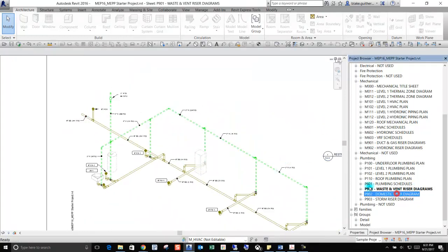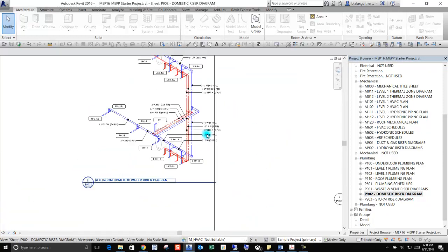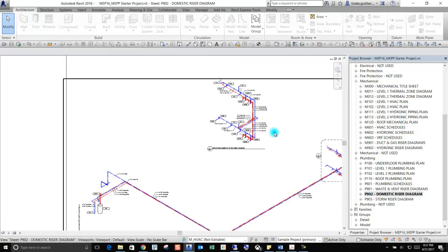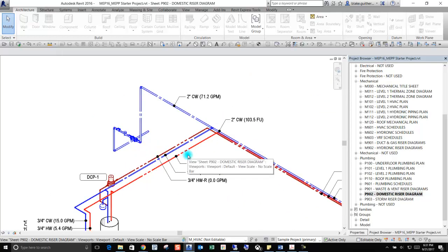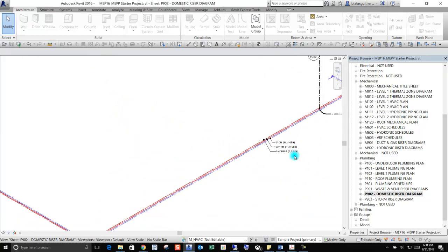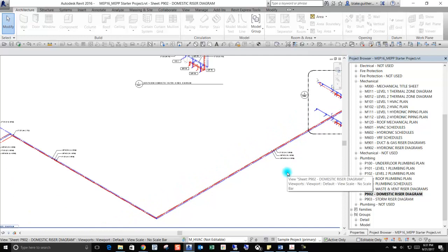And on the domestic side, once again, just further examples of why it's important for these connector settings and getting manufacturers to set them up the same way. We're able to get fixture units throughout the system, and with Revit we're able to do the calculations based upon whether you have flush valves or flush tanks to calculate the GPM in the system. So this is the sample project, fully connected for you guys to digest and play with and try to break and flex values and find out what happens. It's all here as an example for you guys.